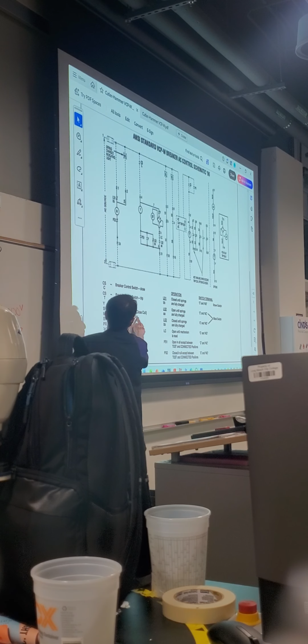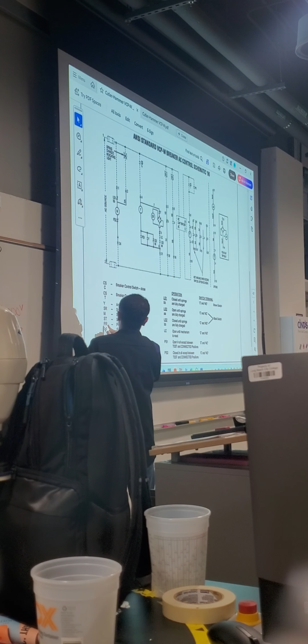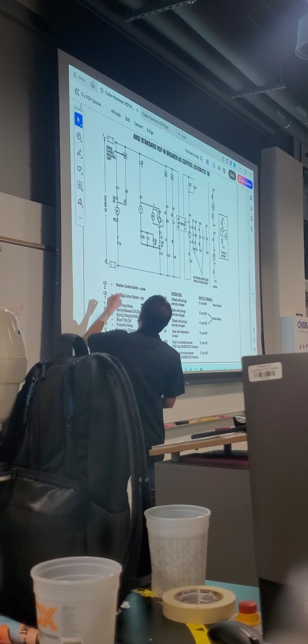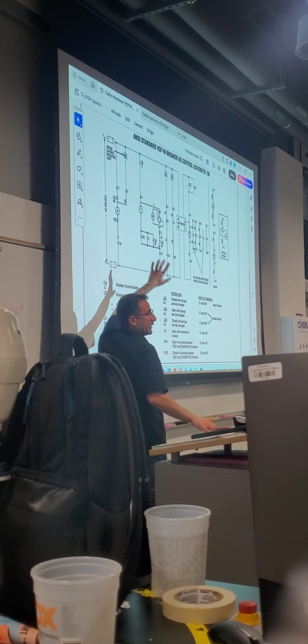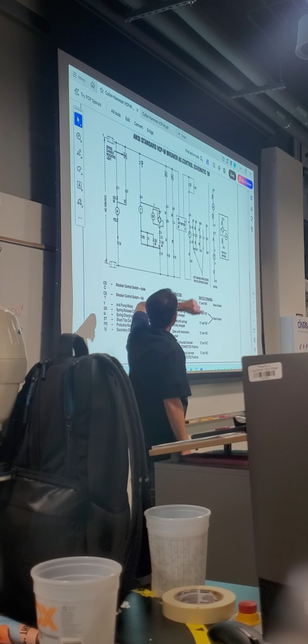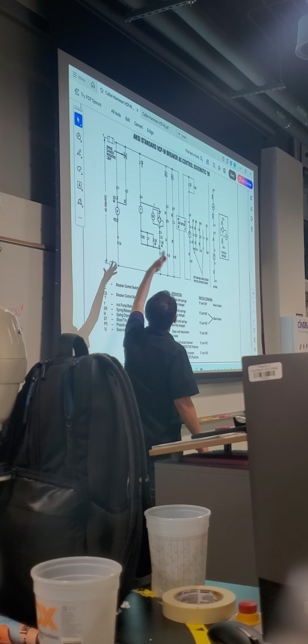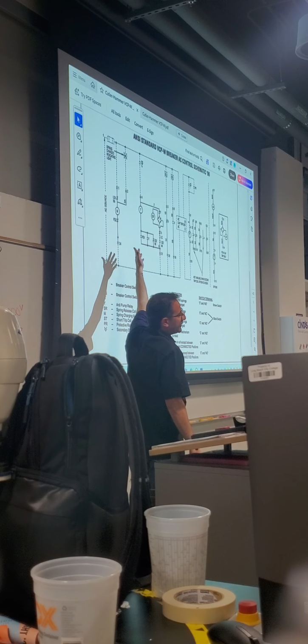So this is what's charging the circuit breaker. SC is the shunt trip coil, PR is the protective relay, and these arrows or chevrons are for secondary disconnect. Again, everything on the secondary. We're gonna be looking at the DC, right? This is AC. So assuming it's AC.